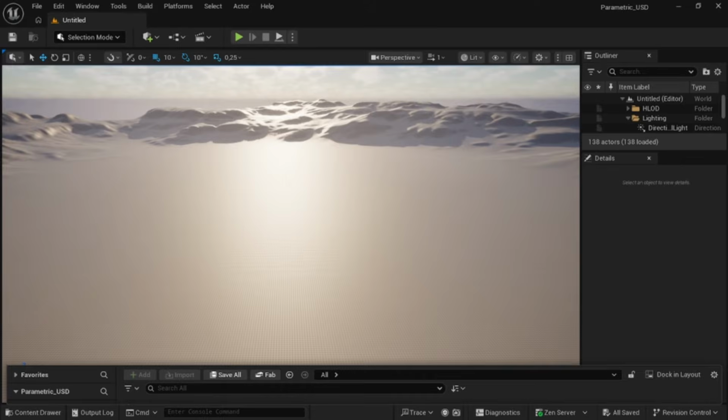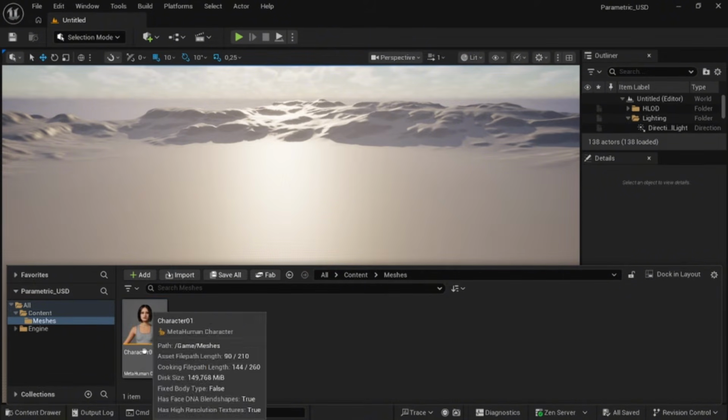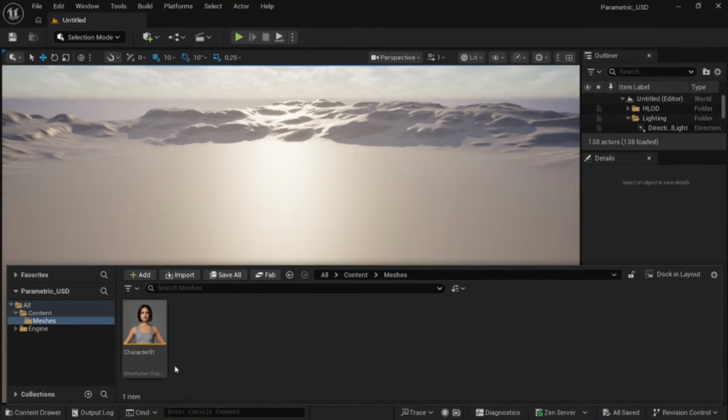Now we will convert the style into a resizable MetaHuman Wardrobe Asset. Open your content browser. In the content browser in Meshes, you can always find your MetaHuman. Here we will always have all the MetaHuman assets stored, and later on we will import the combined skeletal mesh here. But first let's go back to the content